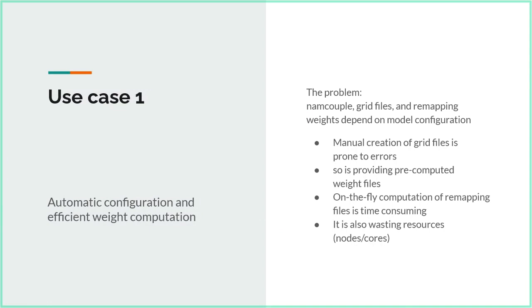It's optimized for your model run, which means, I'm not sure how far I should go into the detail, but Oasis produces the weights for each source-target remapping methods combination always on the source. So if you have a source in your source component that has multiple links, then those weights will be computed sequentially. So we would like to improve on that.